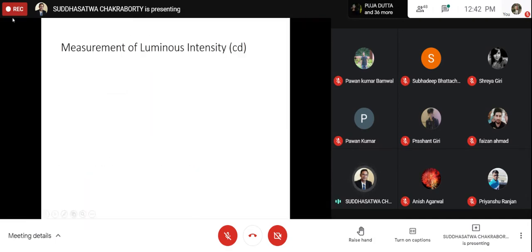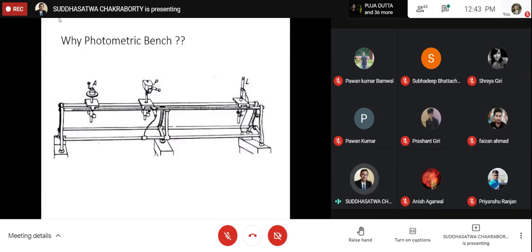How do we get the calibration data? Let's forget about the middle P block. Component A is my light source, which is fixed at its position. L is another point where I will first put my test lux meter, and we will take the data. Then I will replace my test with a standard. Maybe you can do the standard first, then the test, whatever sequence you want to follow. Compare the percentage error. That will give you the calibrated data of your test one, isn't it?